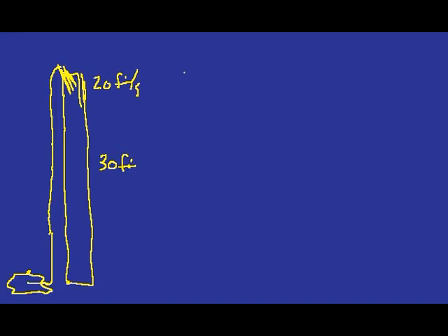So we have the power that we've added. We have a pump down here doing this, and the power that we've added to this pump, let's call that W dot into the pump. W dot is work per time is equal to, well, let's see, how do we raise the energy of the fluid? There's kinetic energy. We'll put the m outside, 1/2 v squared plus g times h for the potential energy.